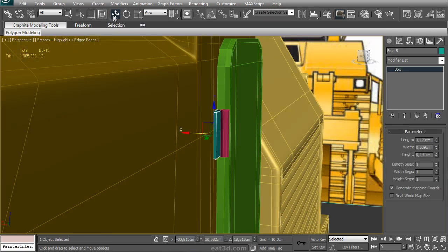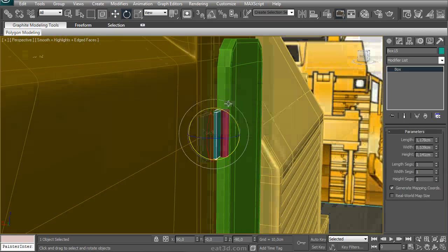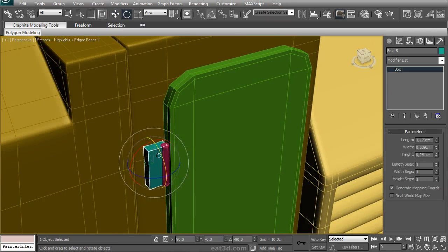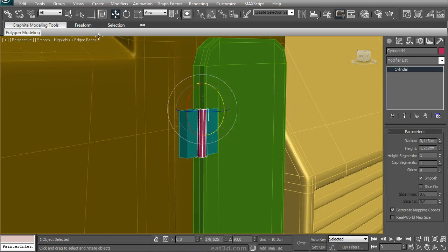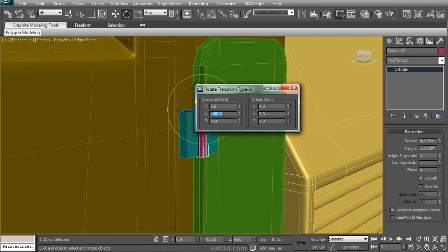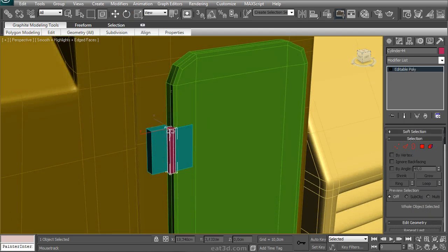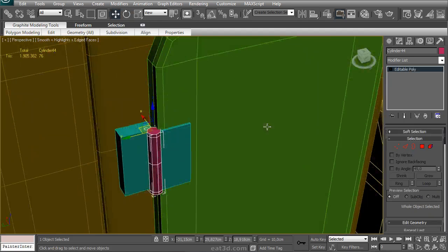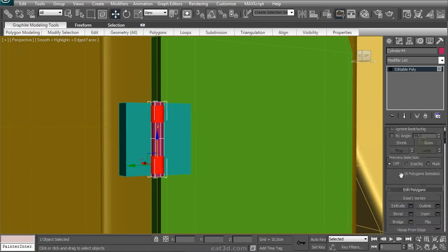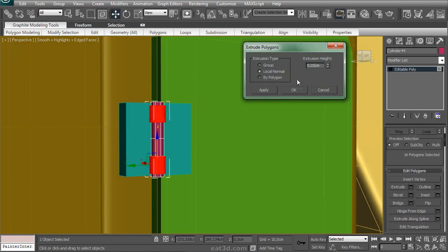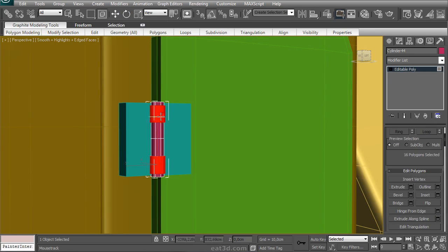Now what I'm doing here is there are of course hinges to this panel for it to hinge across when it's opening. Really easy. Just a few primitives. Positioning these. Make sure they look right. And I used AutoGrid to create these, but AutoGrid might be off by a few decimals of a degree, so I always need to go back and double check if it's not doing something wrong. And this is just simple modeling to get the shape in there, using SwiftLoop to add the control edges. No big deal.